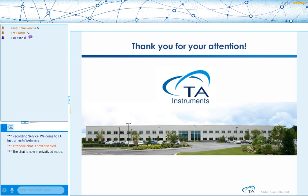And then it's good in the high frequency region to get to the point where G prime is almost constant. So we're getting into the glassy regime. And what this will do is it will establish a number of relaxation times. There's an algorithm in our TRIOS software that will convert the G prime and G double prime data to a molecular weight distribution.